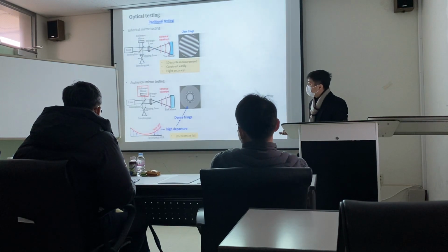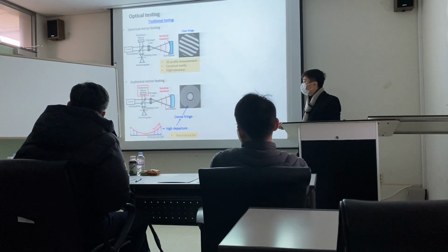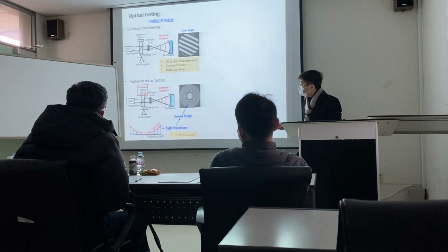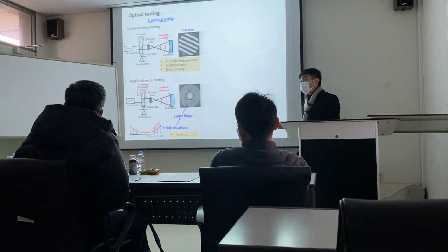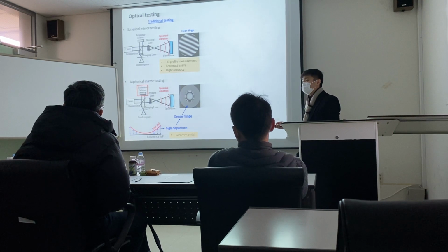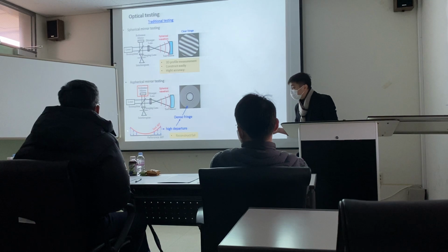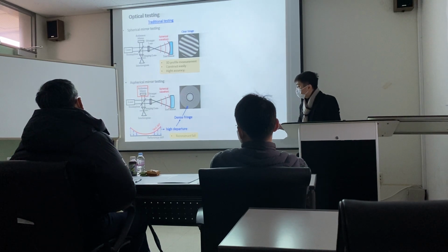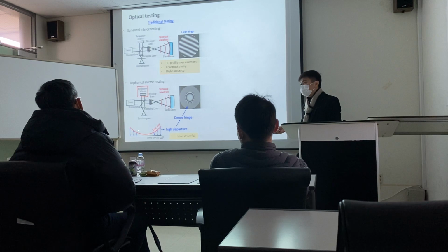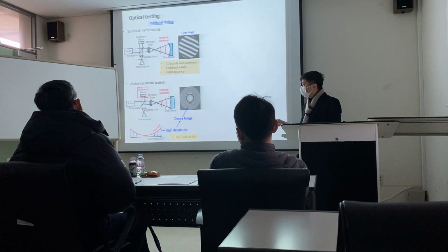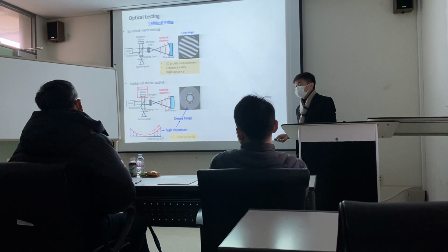However, if we apply the traditional method to aspheric testing, it will be a problem. The reference arm is spherical, and the spherical wavefront has to fit the aspheric surface. So here the reference wavefront and the aspheric one, the red one, differ. The difference between the reference wavefront and the test wavefront we call the departure. When the departure is very high, we get very dense fringes, and with this kind of fringe we cannot reconstruct the surface.